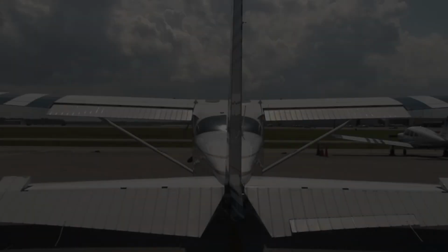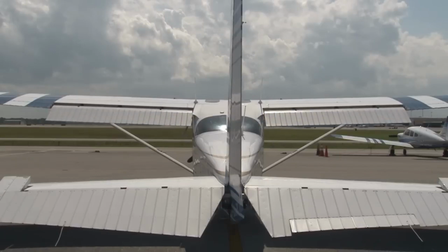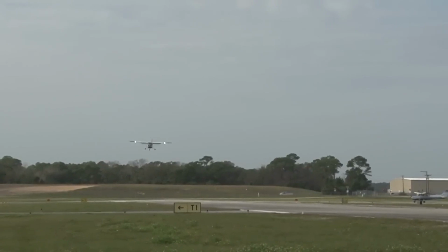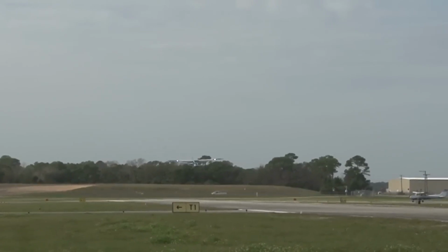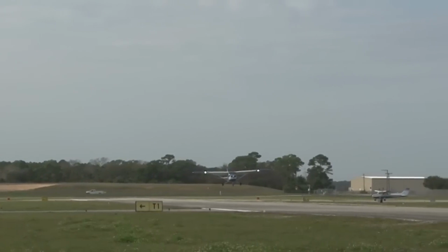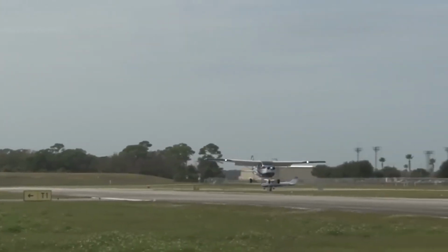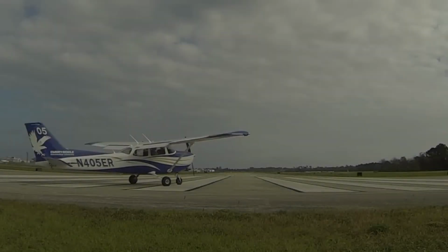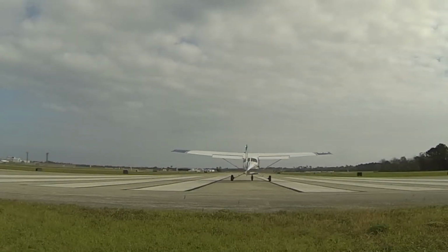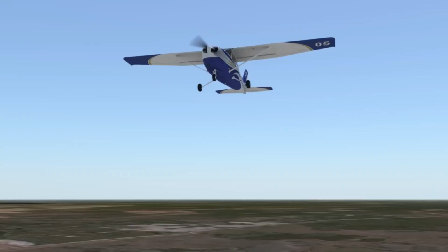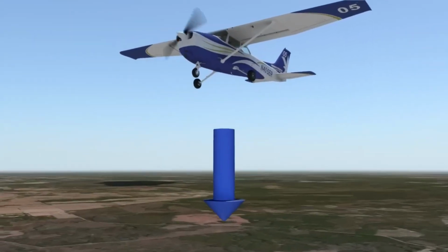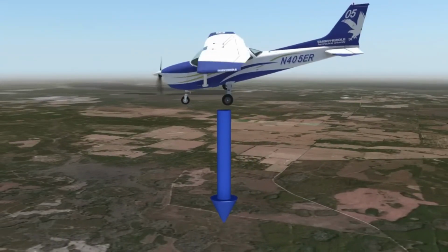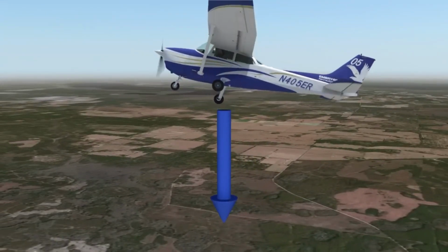Atmosphere. The atmosphere is the envelope of air which surrounds the Earth. A given volume of dry air contains about 78% nitrogen, 21% oxygen, and about 1% other gases such as argon, carbon dioxide, and others to a lesser degree. Although seemingly light, air does have weight, and a 1 square inch column of the atmosphere at sea level weighs approximately 14.7 pounds. About 1/2 of the air by weight is within the first 18,000 feet. The remainder of the air is spread over a vertical distance in excess of 1,000 miles.